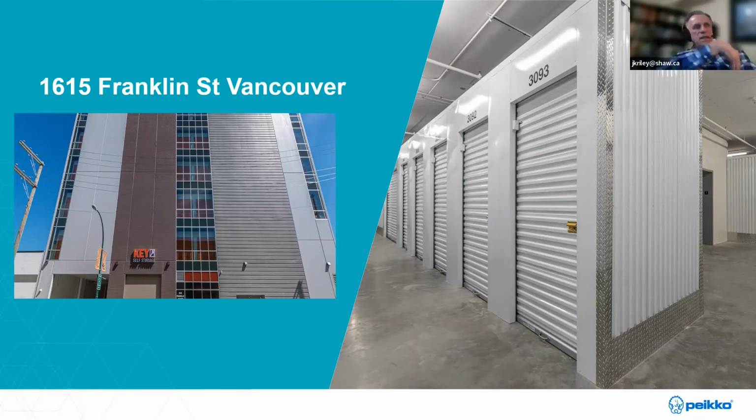So the designers went back and said, okay, what we're going to do is replace it with composite beams in the structure right here. If you look carefully, you cannot see any beams there. Right here, you cannot see any beams in that ceiling space. So they were able to eliminate all the beams and have them all in the floor assembly, just like what you've seen with mass wood. And that enabled them to get another floor in the same building height. So they added one more floor, and that got the FSR from 3.5 to 5.